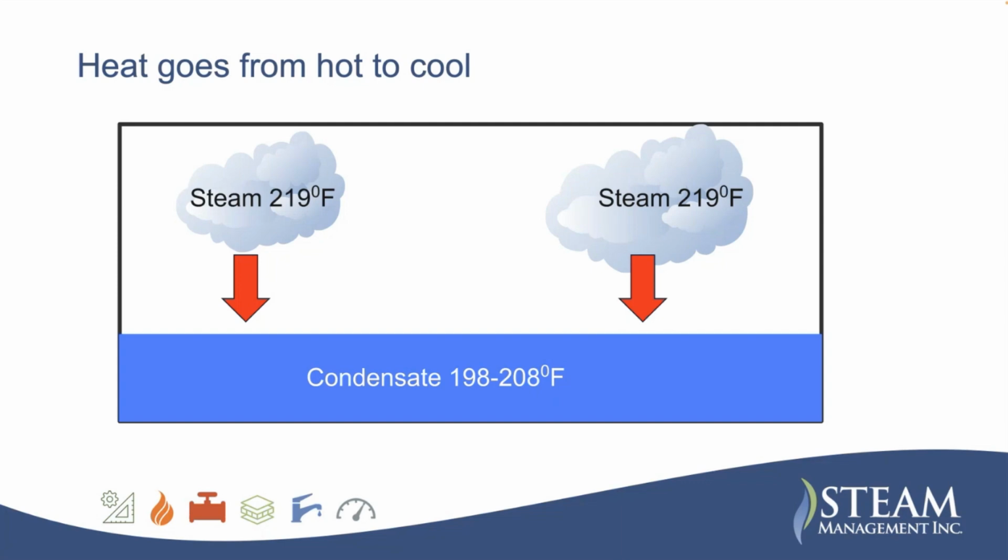A degree day is anytime the temperature is below 65 degrees. But you have to factor out the spring, summer, or early fall, where you don't actually have the heat on, because it'll give you a false reading. So what I will typically do is go from October 15th to maybe March 15th, and look at the degree days in that time. I hope that answered your question.